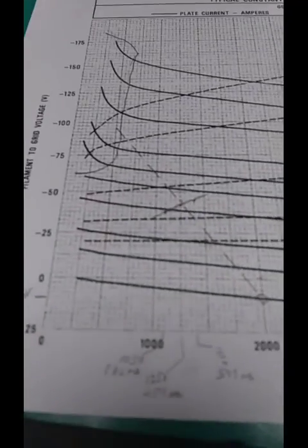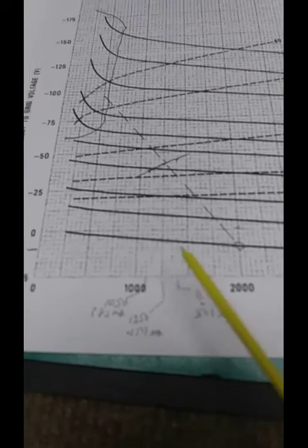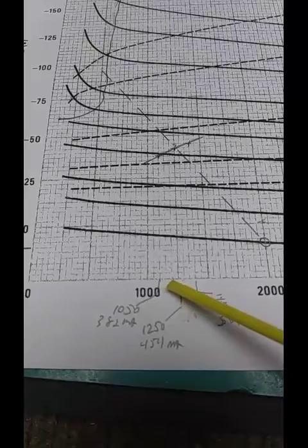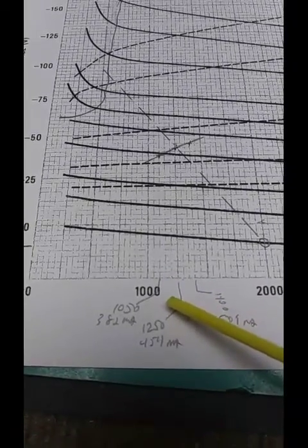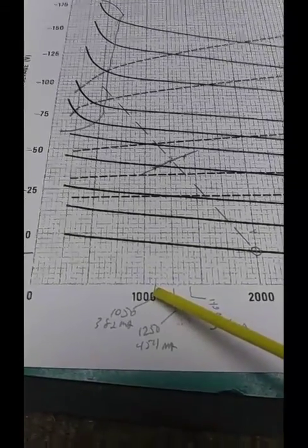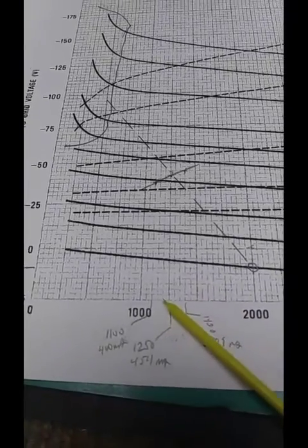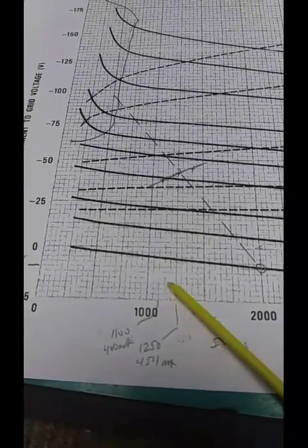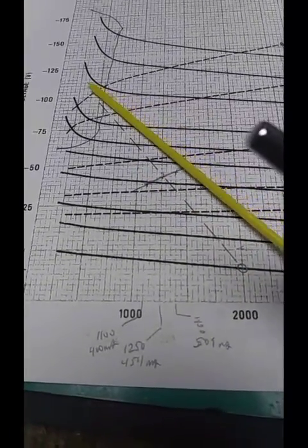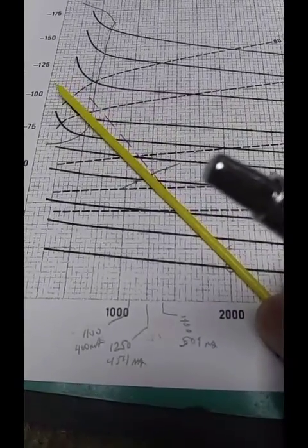And if you want that, then go find the 1000, 1025, 1050, 1075, 1100. Correction, 1000, 1050. Pardon my mistake. If that's what you want, go to 1100 volts, 400 milliamps, project up to this point, and then redraw that line, like such.